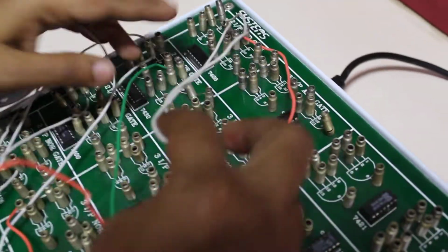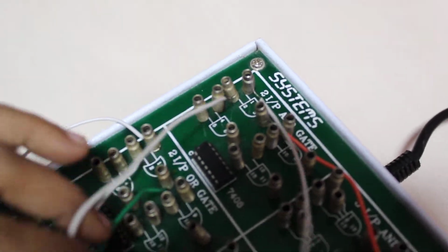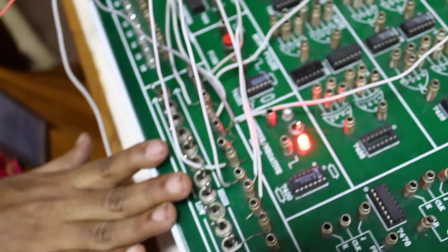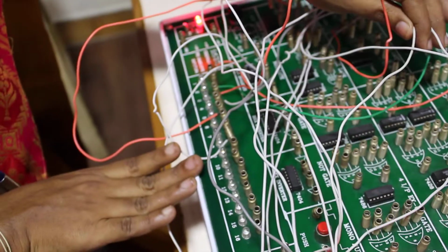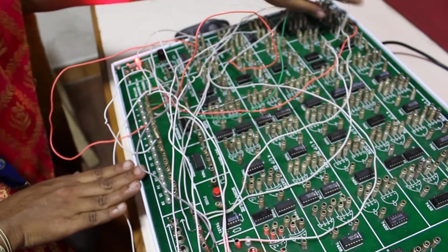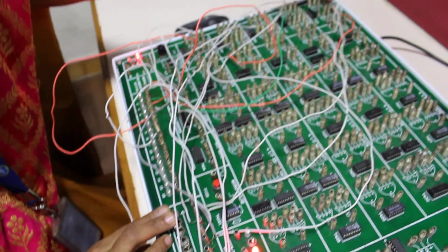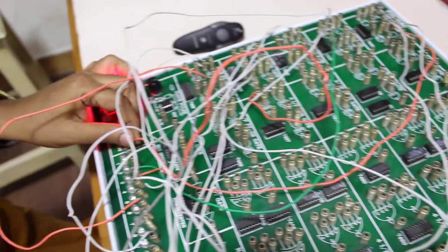Now we'll verify your AND gates. You have a 2 input AND gate. So now 2 connections are given. Here this is the set of input switches, whereas this is a set of LEDs for showing your outputs. You have the gates, you have the inputs, you have the outputs. These are the 2 inputs that have been connected to the first 2 points, and this is the point for the output. This orange color wire shows the output here.